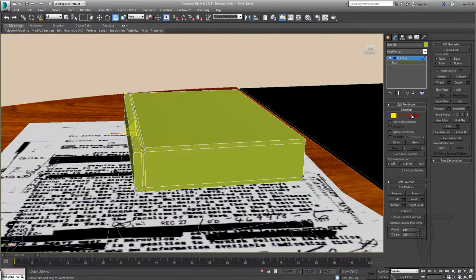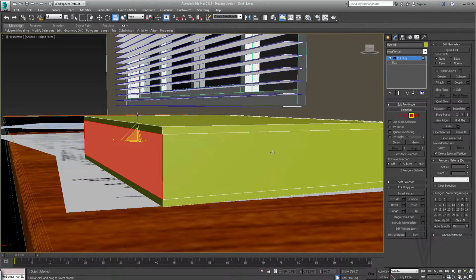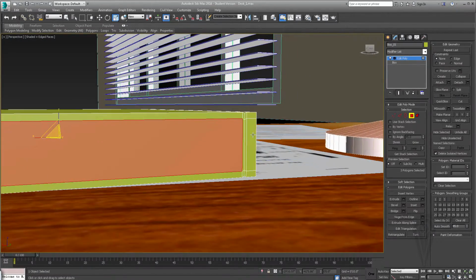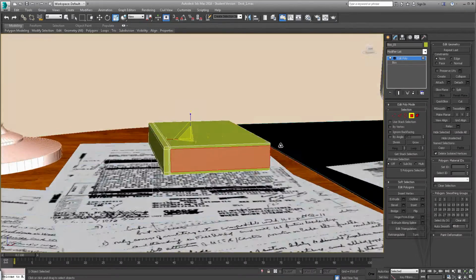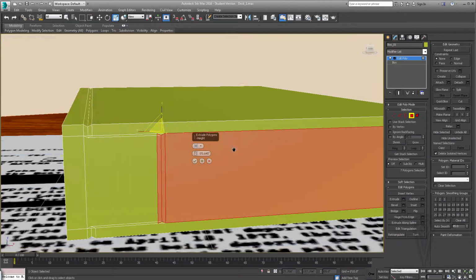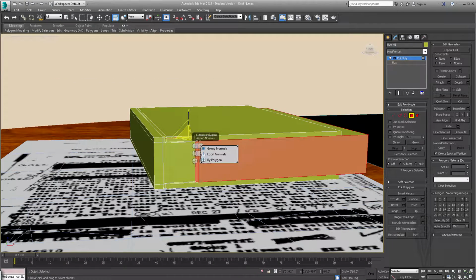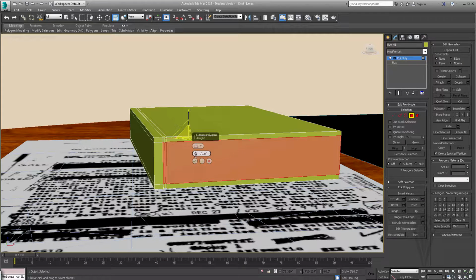Okay. So let's go ahead and go to polygon mode. Select this polygon, this one, and this one. And we're also going to select these 2. Forgot to select them on this side. Okay, we're going to do inset. Actually, no, we're going to do extrude. So let's go ahead and do the extrude menu, dial it up. Not going the direction I want it to, so let's switch it to local normals. And let's dial it down.